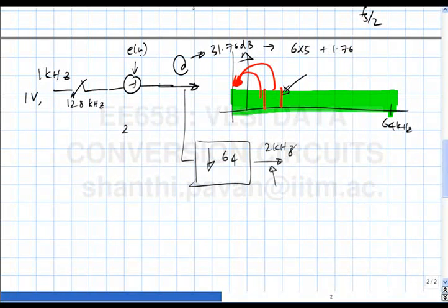If I find the mean square value of samples 1, 3, 5, 7, 11, etc., it must be exactly the same as the mean square value of 2, 4, 6, 8, etc., which means that whether I drop samples or don't drop samples, the mean square value must remain the same. This is the time domain view of the same phenomenon.